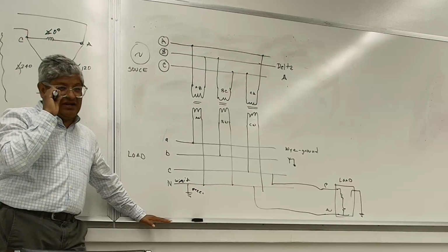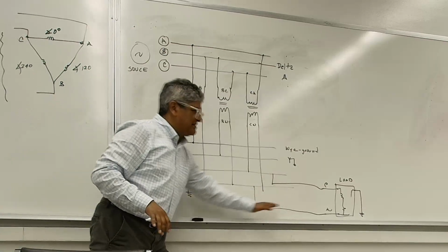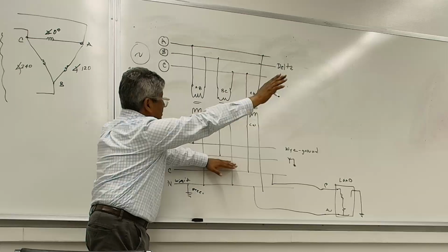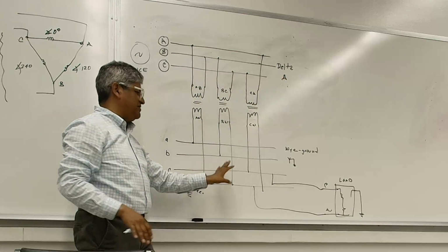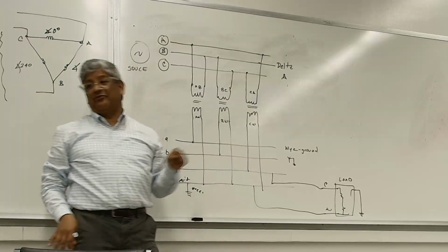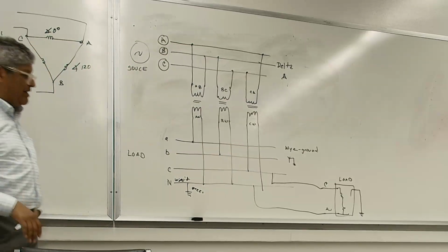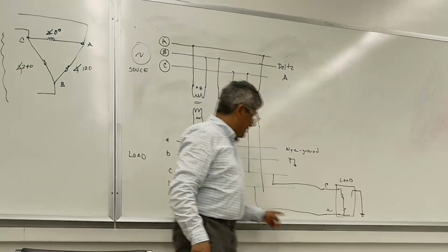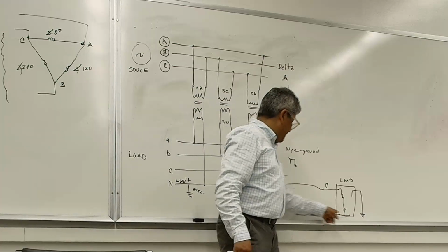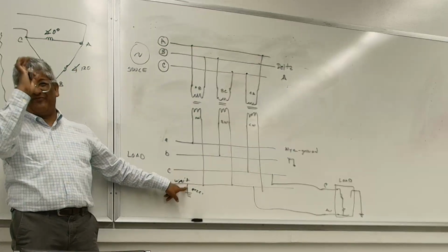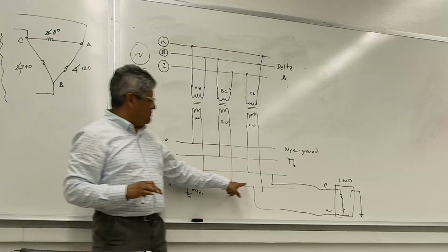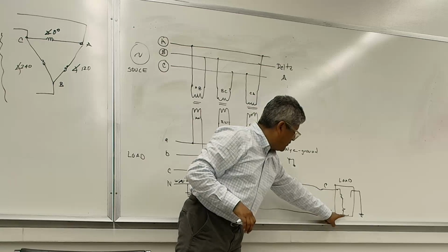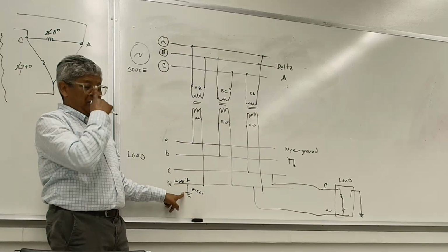If you work for utilities, you don't deal with this side. You mostly stop right here and let the customer do whatever they want once they go in there. So utilities engineers don't often have to see this. But if you are a facilities engineer for a factory, refinery, whatever that might be, you will come across these cases. The reason, once again, is that this neutral right here was supposed to be a zero reference, right? Very tight. Sometimes what happens is that they develop some voltage right here, and this point is no longer grounded or zero, okay?